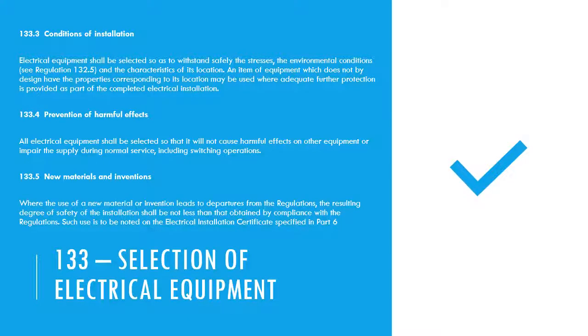We need to think about the condition of the installation as well. We need to select equipment so that it can withstand any stresses or environmental conditions where it's going to be used, external influences. We need to prevent any harmful effects of the equipment being installed. And also, with lots and lots of new materials and inventions, we need to look very carefully at any departures from regulations and any degree of safety. Remember, it must be not less than it would be if the standard was complied with. And any such variations need to be recorded on the correct paperwork.